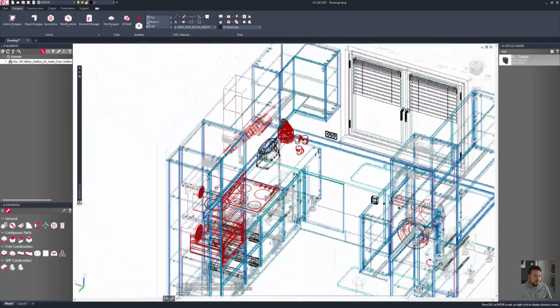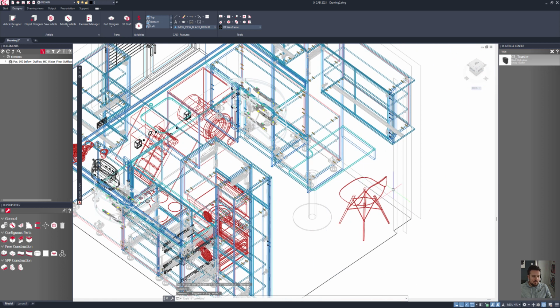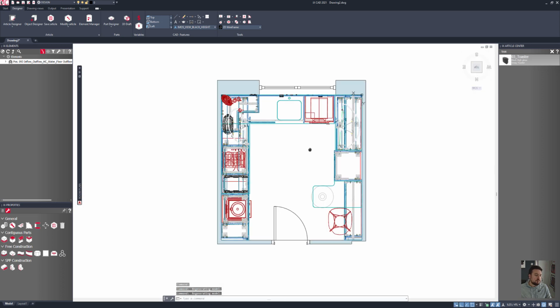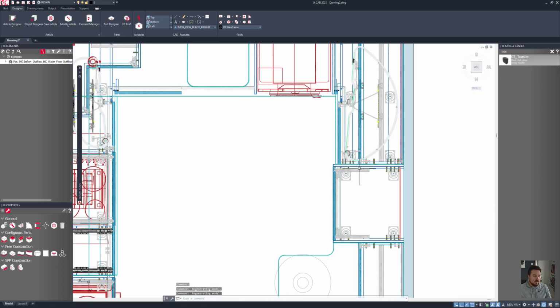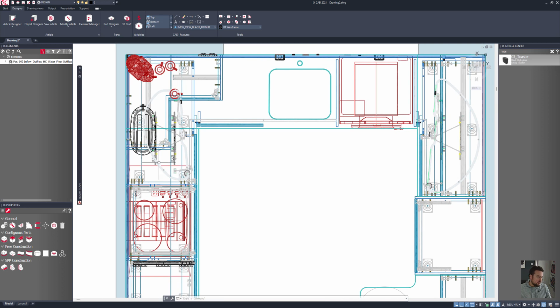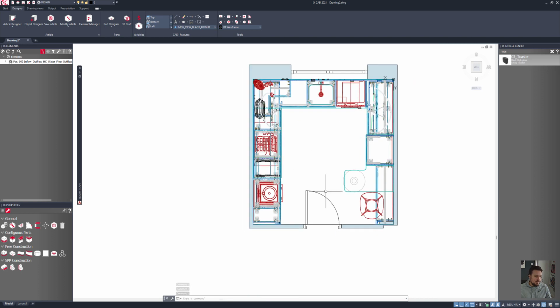This is looking good. So if I was sat on my little chair over here, let's put a camera into position. So what I'll do is I'll go into my top view, and you can see I've got my pull-out mechanisms in here, different sizes because of those doors. They've changed. I need to bring back my sink, so I'll show my sink unit. What else do I need? I think that's about it. Let's put my camera into place and we'll do a quick render.